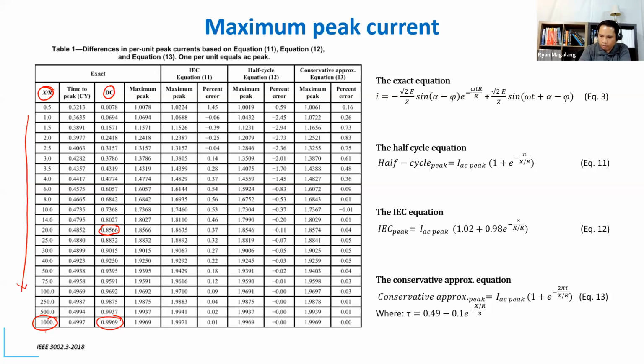Out there in our substations, you'd see 15 to 25 as the common X/R value. For distribution, 8 to 12, 8 to 15 is fine.